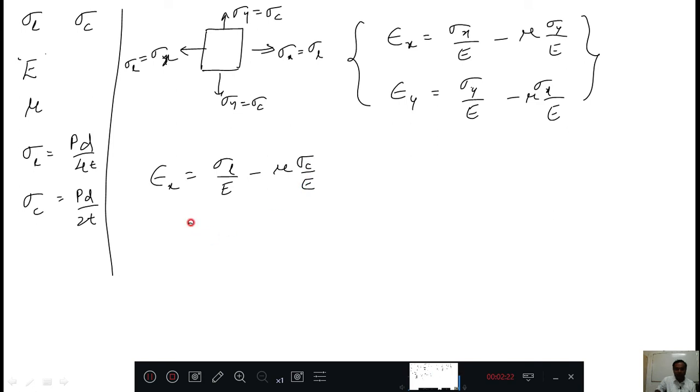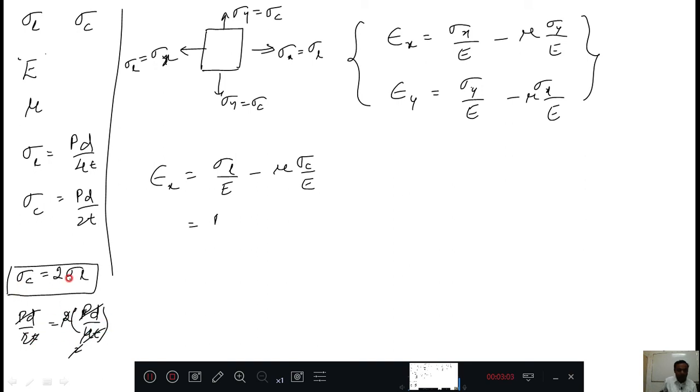Now, what is sigma L? You can write one more thing: PD by 4T is sigma L and PD by 2T is sigma C, so sigma C equals 2 times sigma L. Am I right? Let me check it. Sigma C is PD by 2T, and 2 times sigma L is 2 into PD by 4T. PD cancels, the 2s cancel, T and T cancel, so everything cancels, which means sigma C equals 2 sigma L.